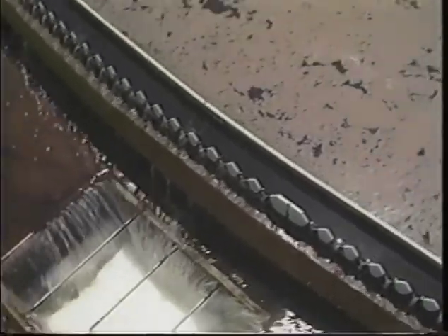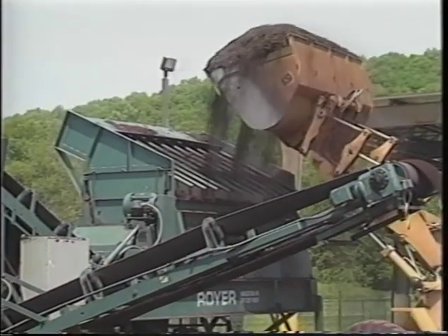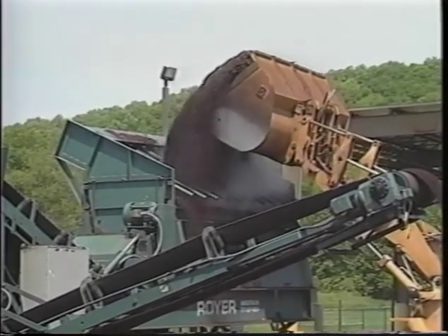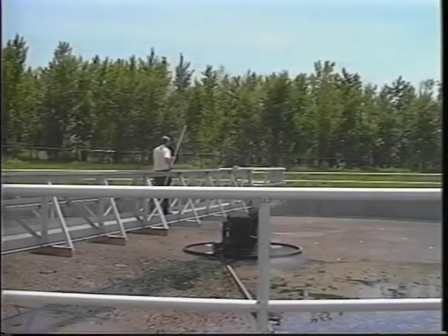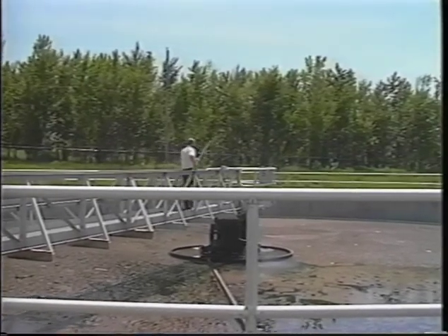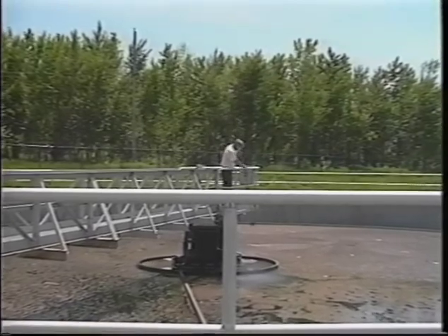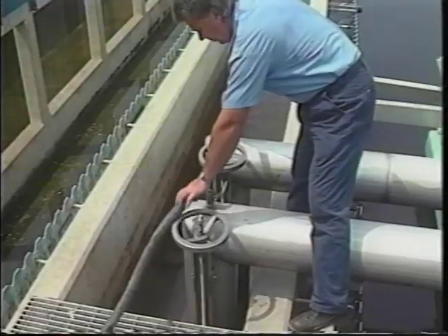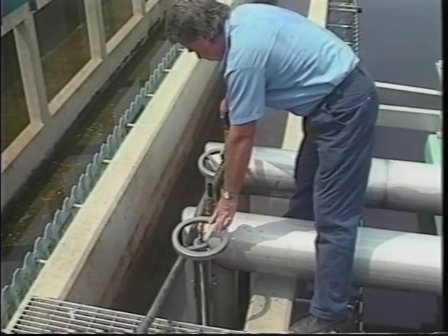The settled microorganisms are then either returned to the aeration tank or disposed of as waste-activated sludge. In any event, the activated sludge is removed from the clarifier by means of the sludge collection mechanism that may utilize pumps, airlift, differential head, or a siphon mechanism to remove the activated sludge from the clarifier.